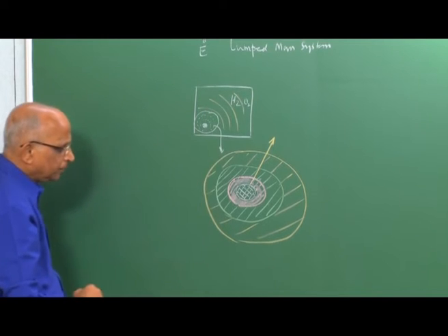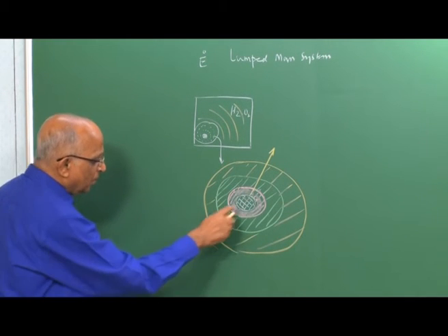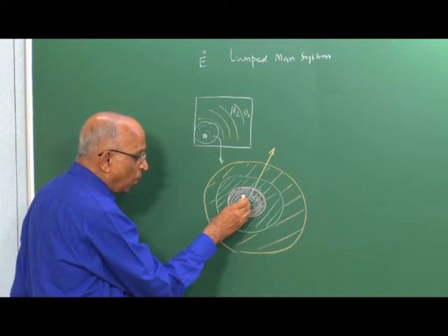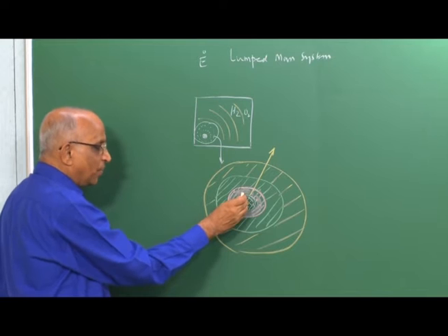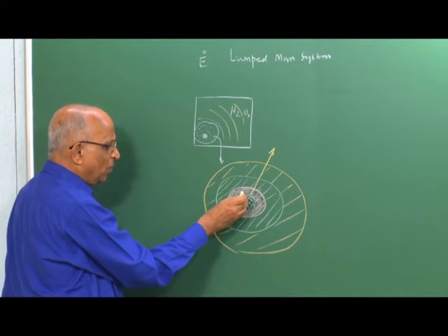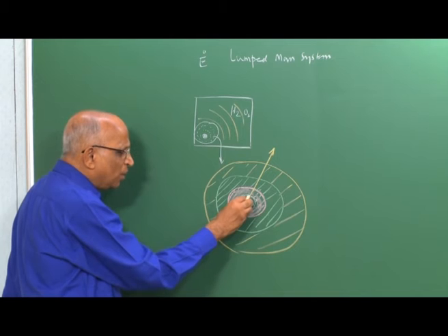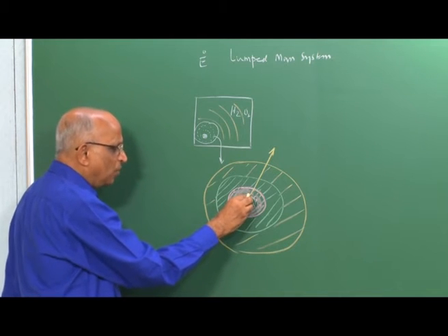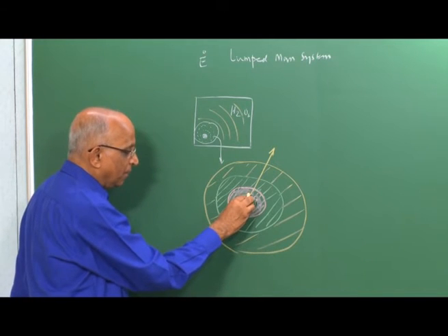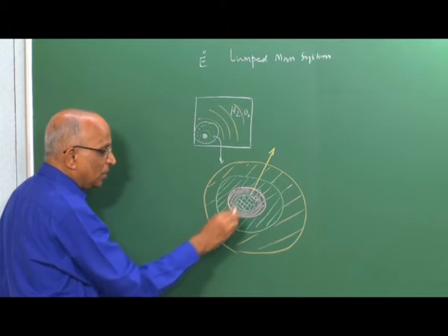This is point 1. Point 2, let us take a look at the energy release itself. Supposing this volume is very small, and the amount of chemical reactions it produces is small, such that when it heats the next layer, it is going to get cool because the heat passes on to the next. Therefore, this hot zone becomes cool, and if the volume is insufficient, or the amount of energy or chemical reactions here is insufficient to maintain its temperature as it is heating the next layer, what is going to happen?